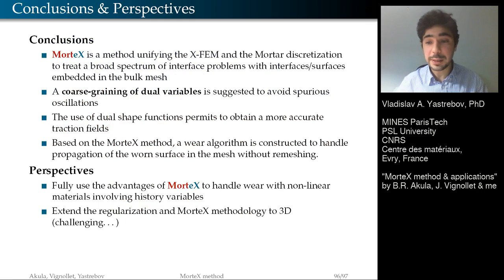I will conclude briefly. The MorteX method is a new method which allows us to solve various interface problems, mesh tying, contact problems, frictional contact problems, and wear. Wear problems require some specific algorithms, because in order to propagate this virtual embedded surface, you need to handle it with care, with caution, because we need to take into account local normals and so on. I didn't explain in detail, maybe next time.